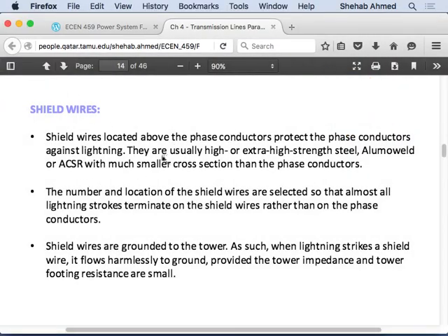They don't carry current for a long period of time, right? Then you don't really need that. Again, the electrical equipment is typically rated for 2 things, right? Either heat dissipation limit, or a physical phenomenon, a physical property. Physical phenomena would be, in the case of conductors next to each other, the insulation between the conductors, right? But here the conductors are up in the air, right? So we're not worried too much about the insulation between conductors. We're worried about the insulation between the conductor and the tower. So we use these insulators.